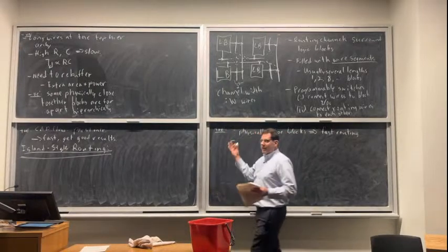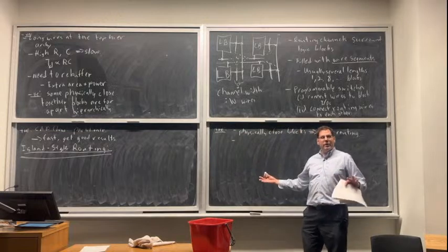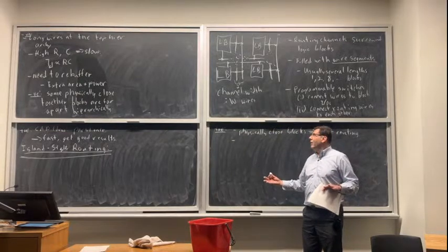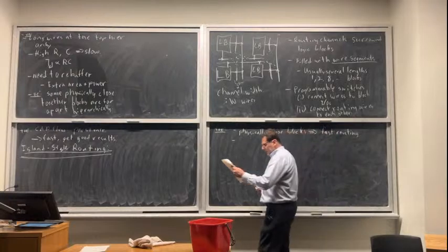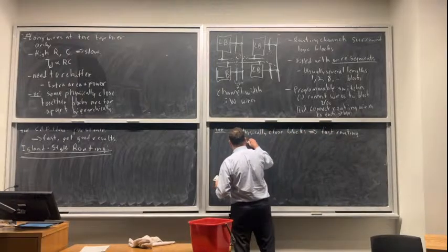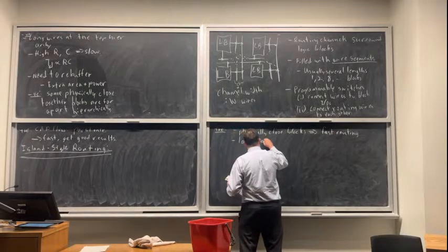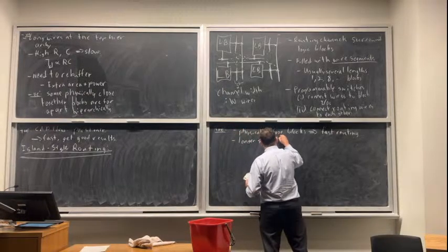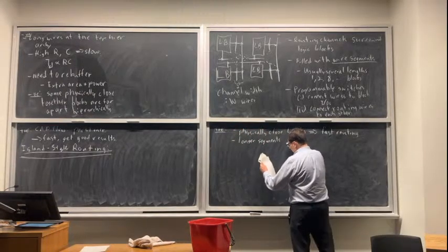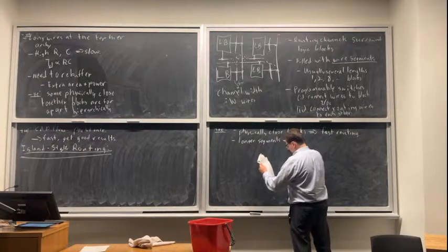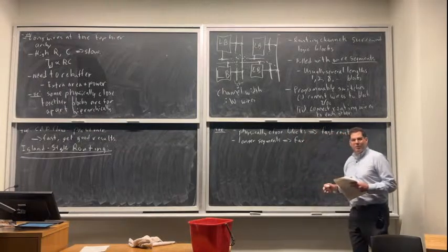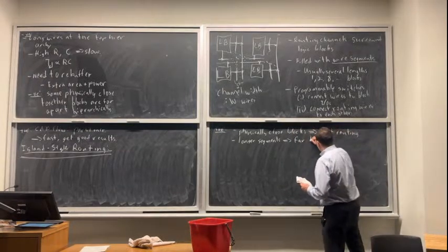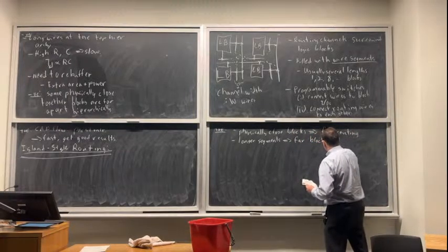Now, the downside of that could be that maybe you go all the way across the chip, which is going to happen once in a while. It could be really slow, and that's mitigated exactly the way you just said. To mitigate going a long way, we have these longer segments. So that means that you'd rather not be far apart, but far away blocks still have a reasonable routing choice.